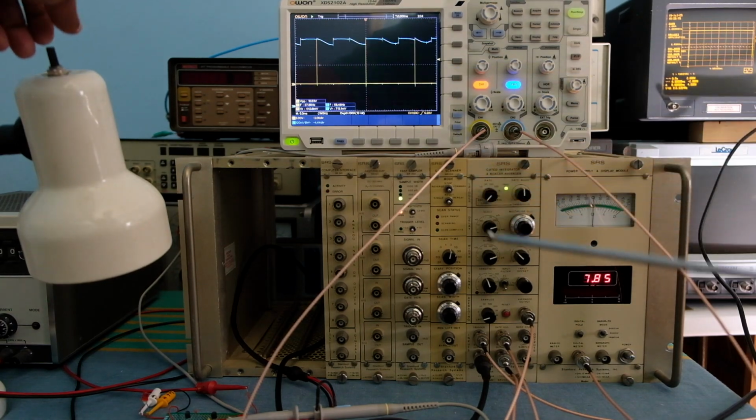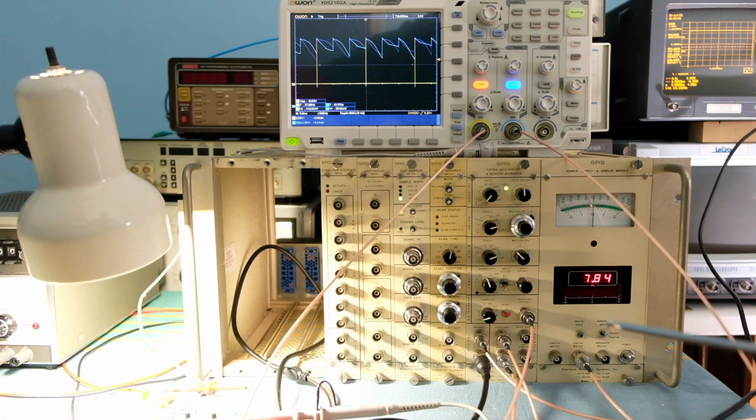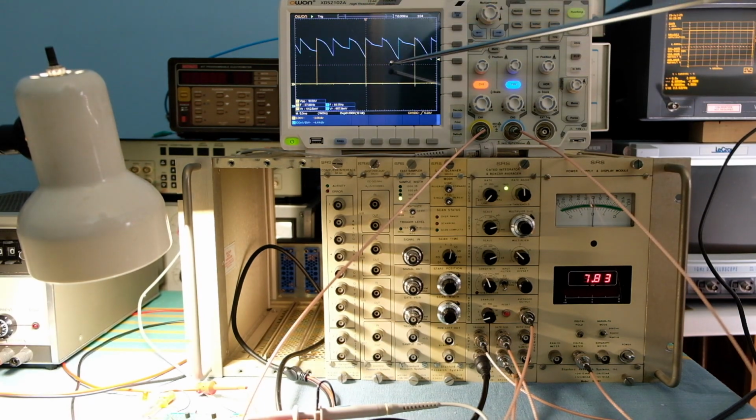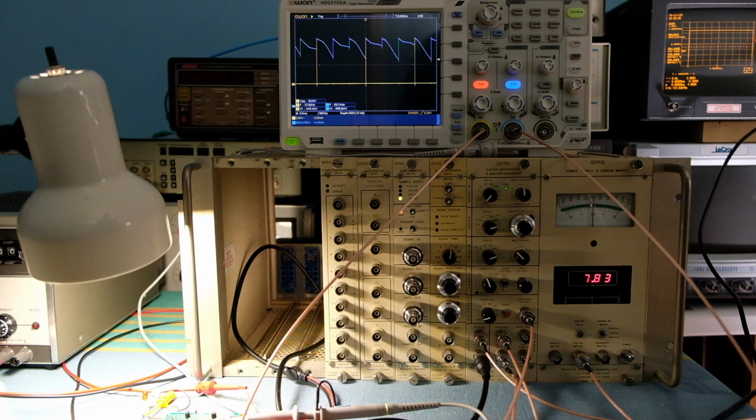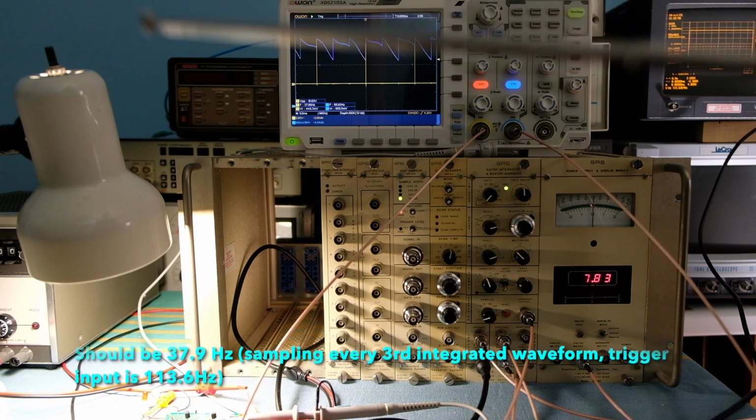So I'm going to now turn on this light, and you can see that the voltage will have a significant change immediately. And now this is the actual slope you can see coming off the discharge of the capacitor, still corrupted by the environmental noise pickup of 60 Hertz kind of noise here. The frequency of the trigger is around 120 or 130 Hertz or so, which is away from the 60 Hertz, 120 Hertz, and those kind of harmonics of 60 Hertz.